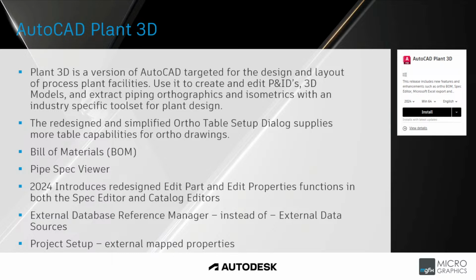2024 introduces redesigned edit parts and edit properties functions in both the spec editor and the catalog editors. Edit the parts within the selected family for inclusion in a spec sheet or catalog. In the spec sheet or catalog, set the property definition for the selection part sizes and the current part class